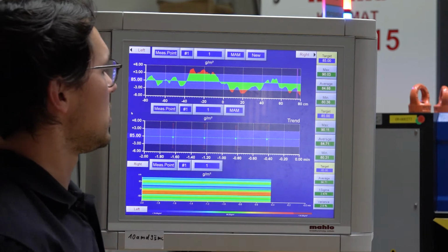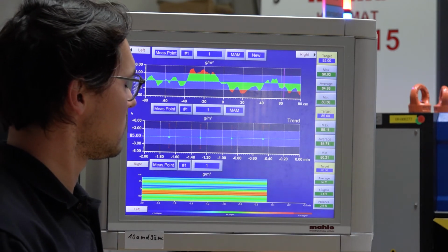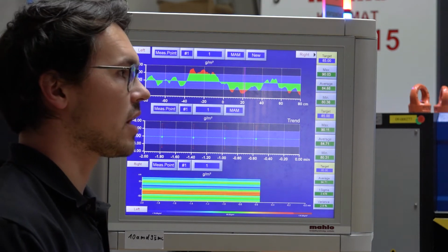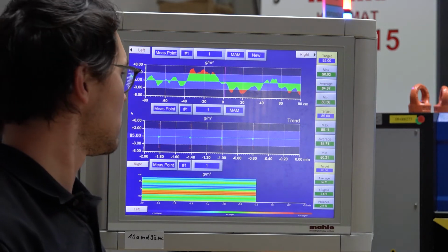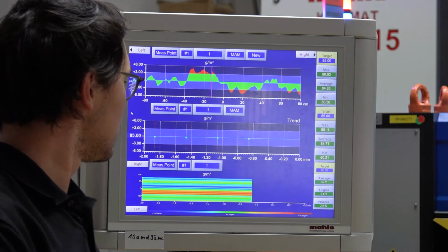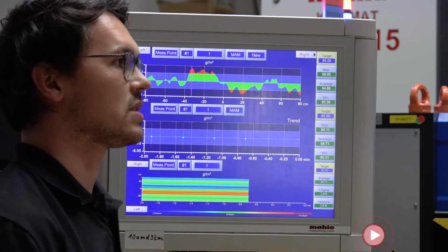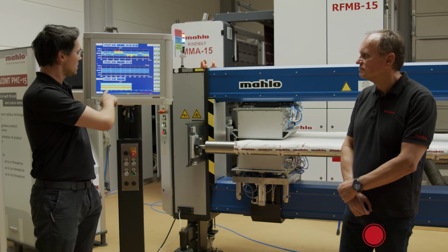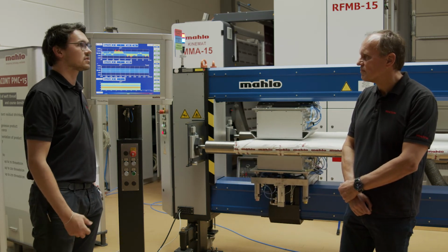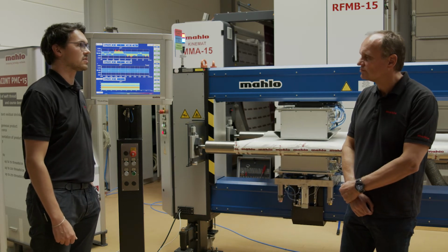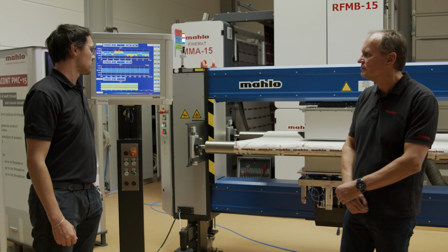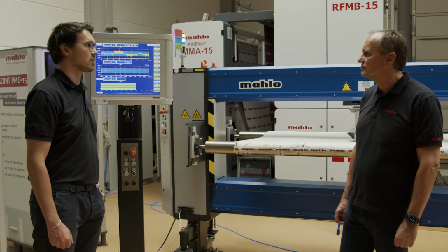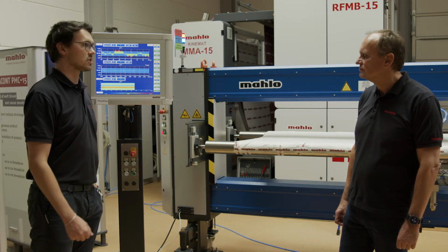In the middle, we visualize some kind of statistic reports, the accuracy or the variation coefficient. And at the bottom, also good information is the length of the product, where you can clearly see, shown by different colors, whether your product is too high or too low in the basis weight measurement, and therefore whether the operator of the production machine needs to adjust some settings to get better results or more averaged results.